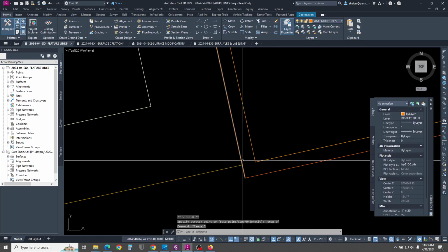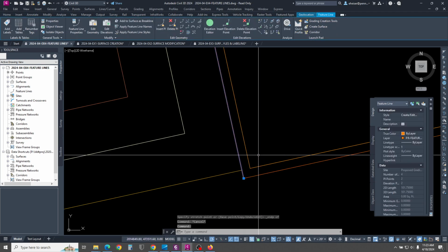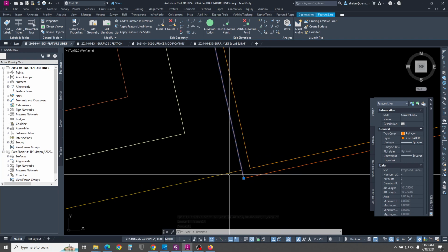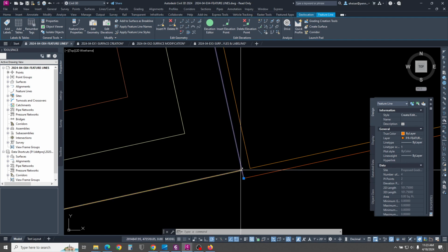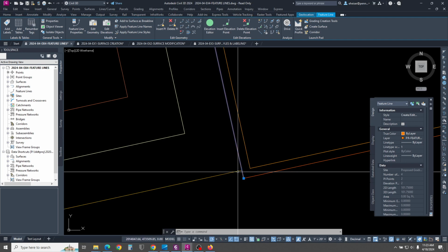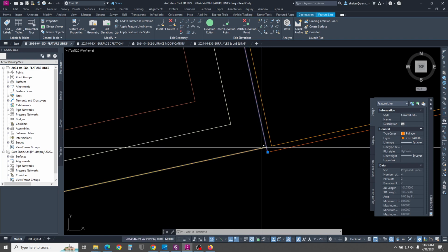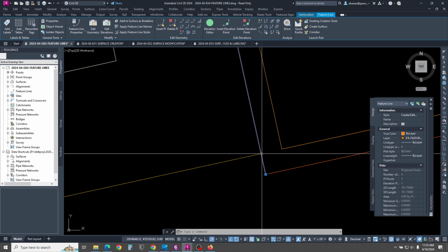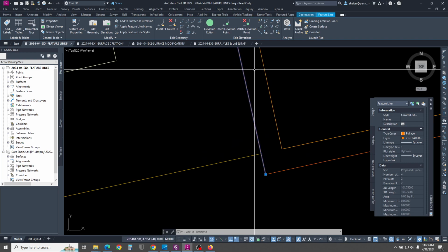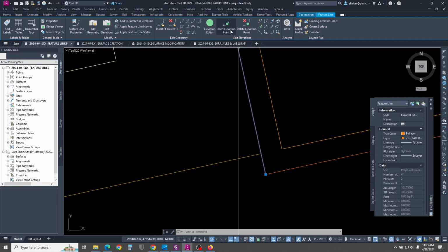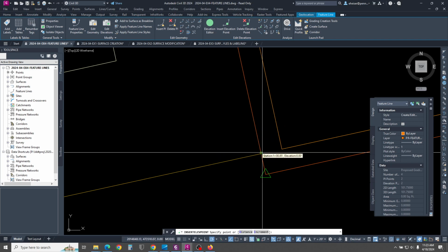Now to add an elevation point, which is a point of grade break or a point of intersection with another feature line where you don't need to make geometry change. So like a point on a line, we're going to add it to where this sidewalk point intersects with our curb. So I clicked on the feature line, it brought up the menu. I'm going to go to Insert Elevation Point. Click on that. You just object snap where you want it.